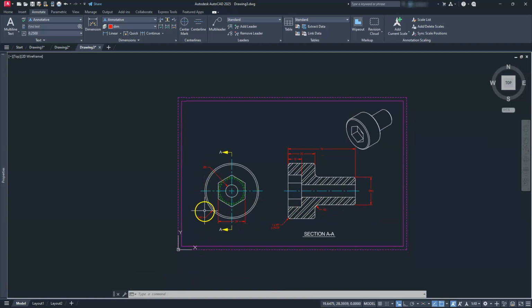So we have all of our dimensions on. We have a section line depicting this section. And remember that the section should typically, most likely, be shown on the opposite direction of which way your arrows are facing. So that's why the arrows are going this way. All right, we have that shown. We have our hidden lines shown. We gave them the size of the polylines. We gave the chamfers, and I think we are actually completed with this drawing.